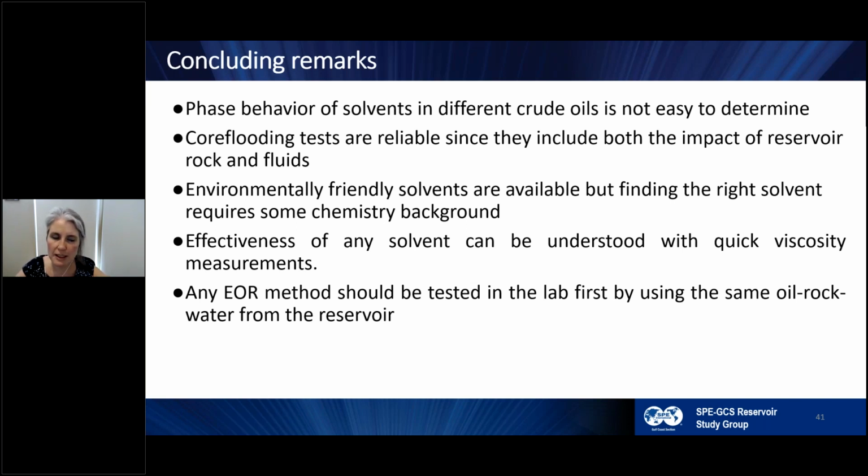If the miscibility will happen in your reservoir, it is better to conduct miscible flooding, core flooding tests, by considering the real reservoir oil, putting a sample of real reservoir oil, reservoir rock, and reservoir water in your core holder. I didn't show the impact of water salinity in the reservoir, and it will have an impact as well.